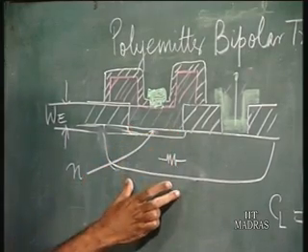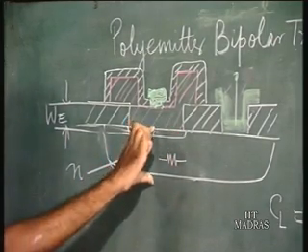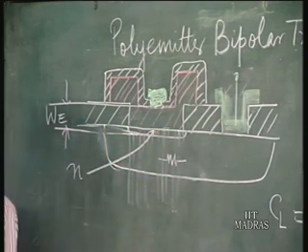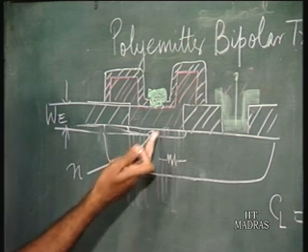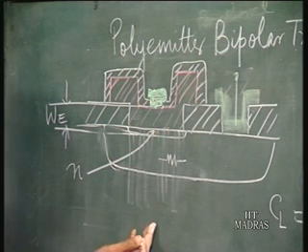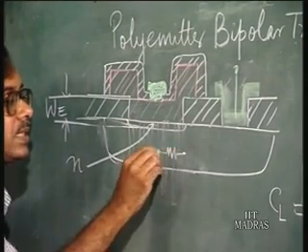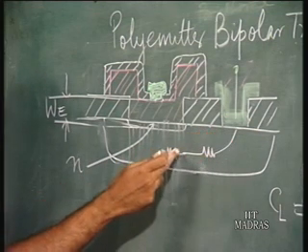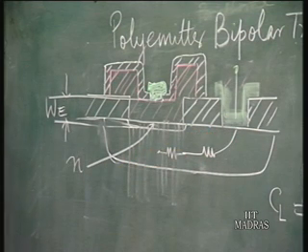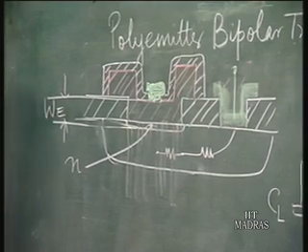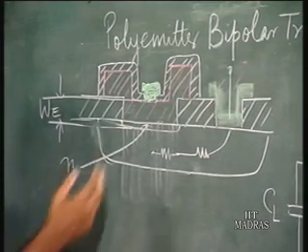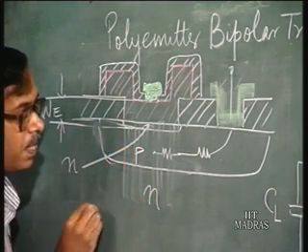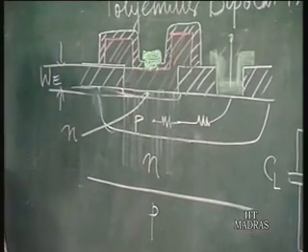So this is the intrinsic transistor region, that is, the region where you have transistor action. So this part of the device is called the intrinsic region. Here you have the transistor action taking place. So this is the intrinsic base resistance, and then you have an extrinsic base resistance, that is from the contact right up to the intrinsic device region. Then you have emitter resistance. Here this is the P region for the base, you have the N region, and then also you will have the substrate, which is again a P.